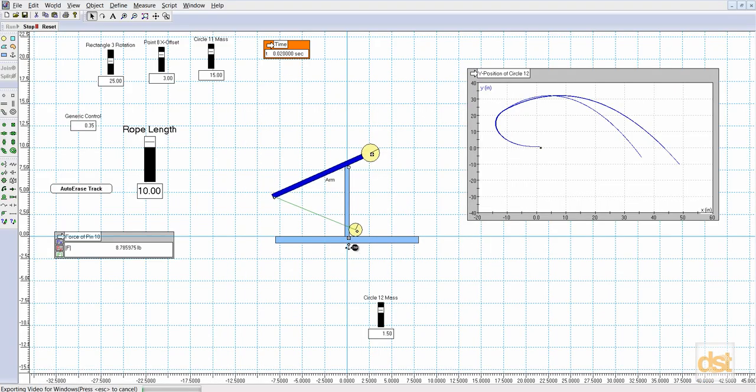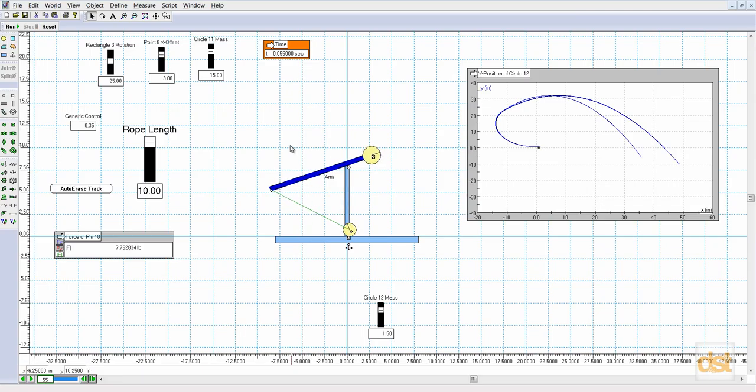And it's starting out slow here because it's writing frames out for all these different steps. But what that's going to do is save a video file of our animation. I'm just going to go ahead and stop it. That will save an AVI file that you can open up and play back. It will capture everything that's on the screen in the graphics area. It will not capture any of the tool palettes or menus.